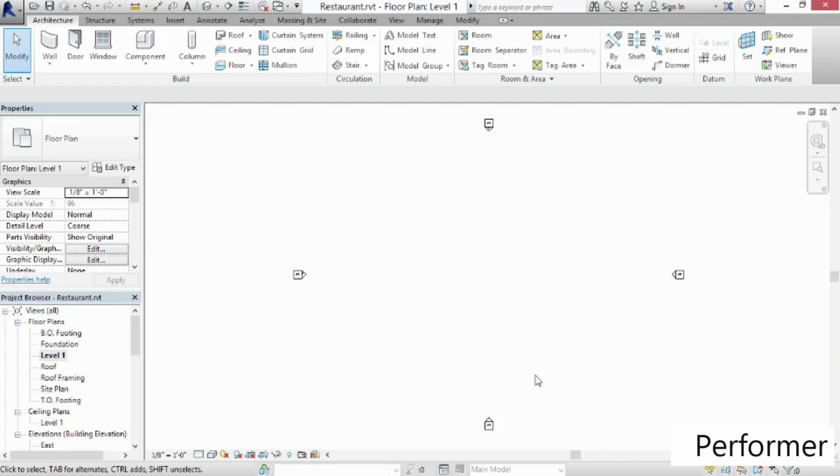So when you want to create a new project in Revit, it's as simple as choosing an appropriate template to base your project on. Once you've got that template opened up, you can save it, give it a name, and then proceed to start adding your building geometry. So in the next chapter, we'll begin adding geometry to this project and building our building model.